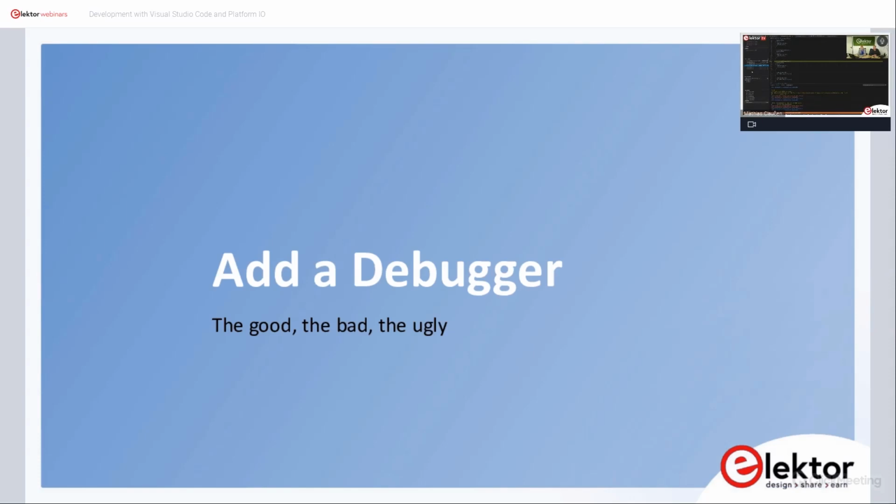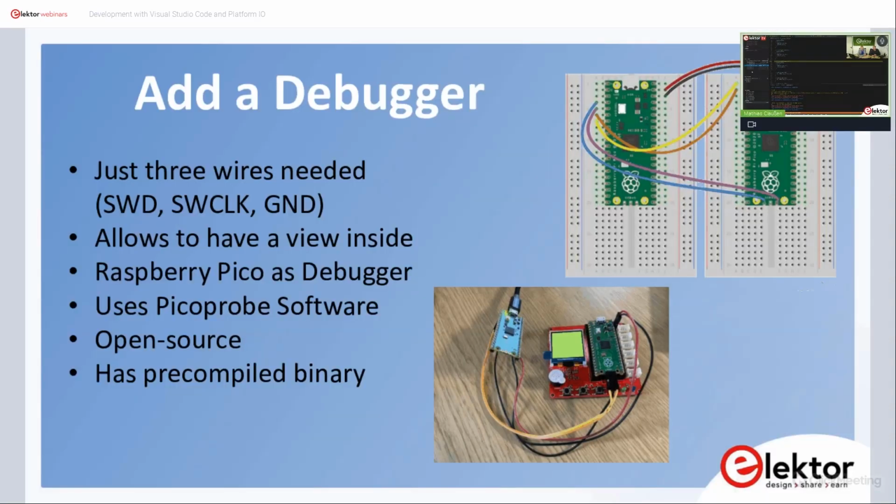Another question: are breakpoints also possible in Flash? Yes, you can set a breakpoint with a breakpoint unit of the MCU. This breakpoint location can be in Flash. If you're having more breakpoints than the CPU supports, there are methods to do so. No, that's not supported with this combination. So that's if you're running out of hardware breakpoints, that's it.